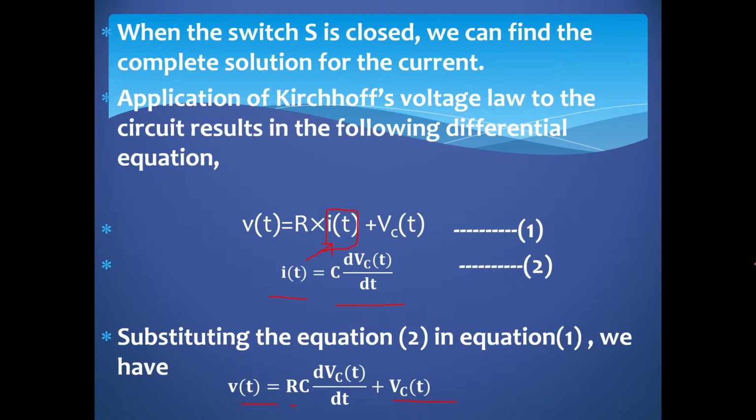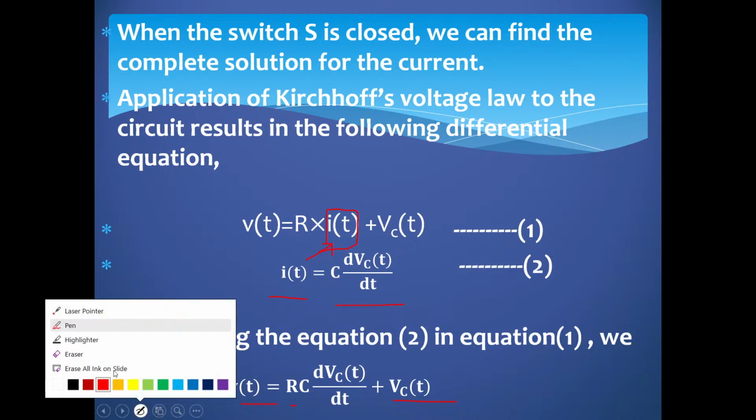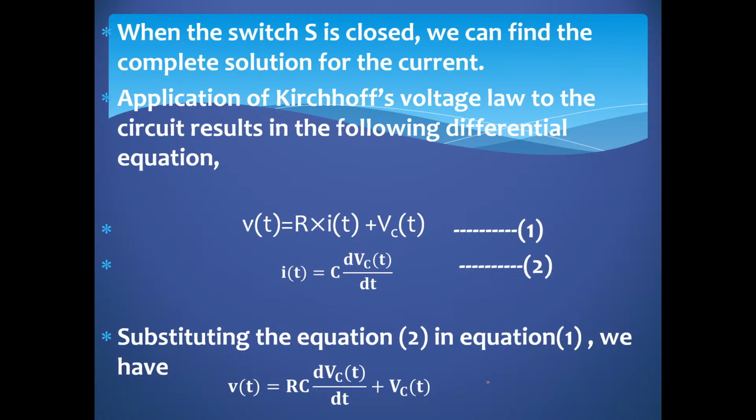Now we have got an expression here. What you have to do now is go for Laplace transformation. What is the Laplace of V of t? Can anyone mention in the chat box? If you have heard the previous session, Laplace of V of t is V by S. V is constant, magnitude is constant. We are assuming a unit step input here, so V into 1 by S, that is V by S.